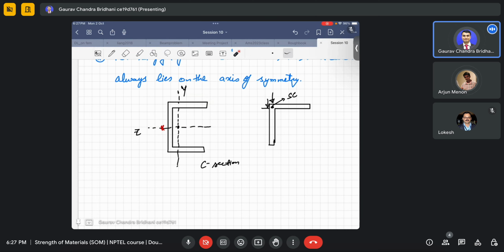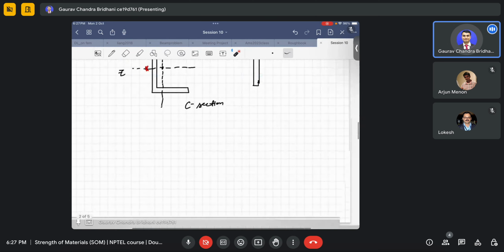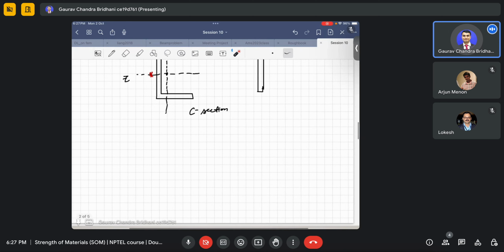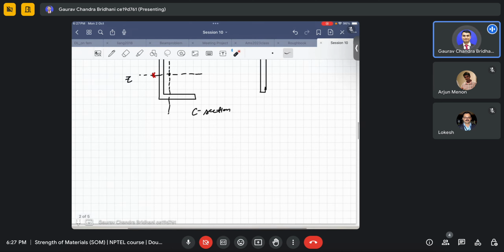Okay, thank you. So now what I was saying, let's write the formulae for the unsymmetrical bending, because it's a very important formula, and I'm glad that the professor has given that full formula, because you can find the bending stress, that is sigma x, using that formula. You can use this for any case, whether IYZ is there or not, means if there is an unsymmetry in the cross section, as well as if there is an unsymmetry in the loading. So you can use it in both cases. I will tell you the meaning of both.